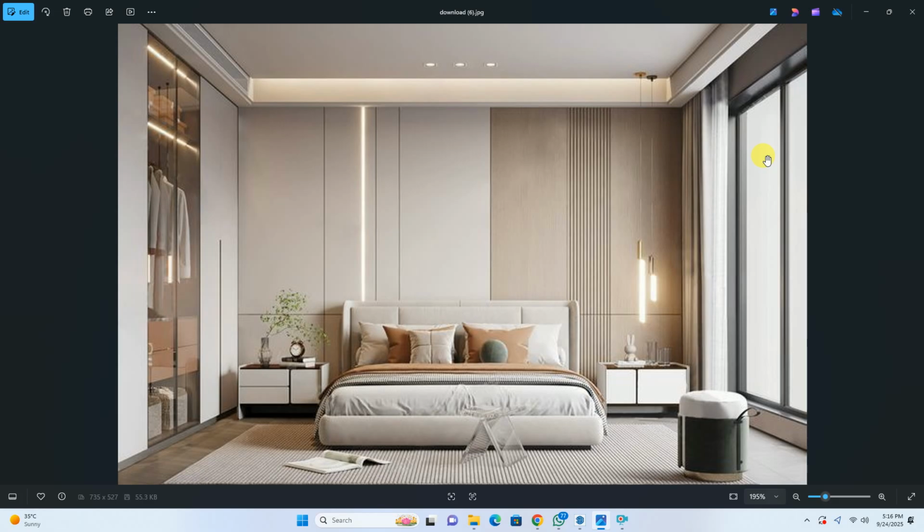Standard size is 8 feet. The maximum UPVC that we can get is 8 feet. Above that, we have to join multiple sections. So for that, we can get a single glass structure like this. If we have multiple heights, such as a larger height segment, then we have to provide some base frame structure for that. So that's why for high heights we generally use aluminum profiles.